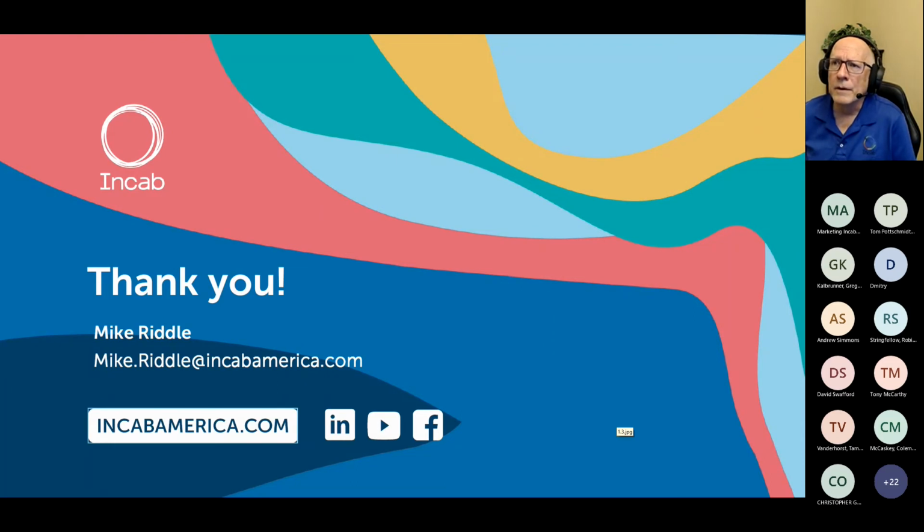If I had the current and I want the rating to be 100 K squared seconds, and to keep the math super easy, I say the duration is a second. Well, then I'm saying my current would be 10, because 10 squared is 100 times 1 is still 100. And that was the rating I wanted.